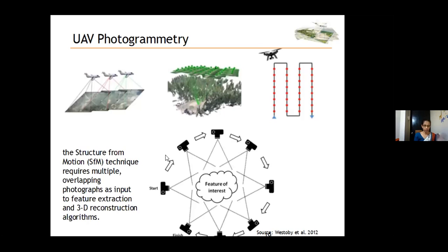Moving from that to modern photogrammetry, which uses structure from motion techniques. As long as the object is viewed from multiple viewpoints in many overlapping images, we can automatically generate a massive number of tie points. We do not need to know camera locations, and it is not necessary to know how far away it is.